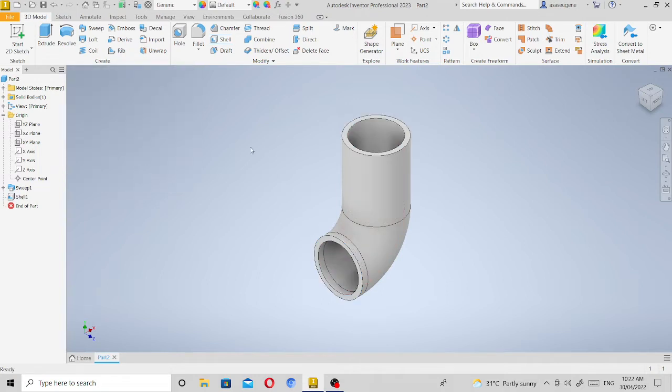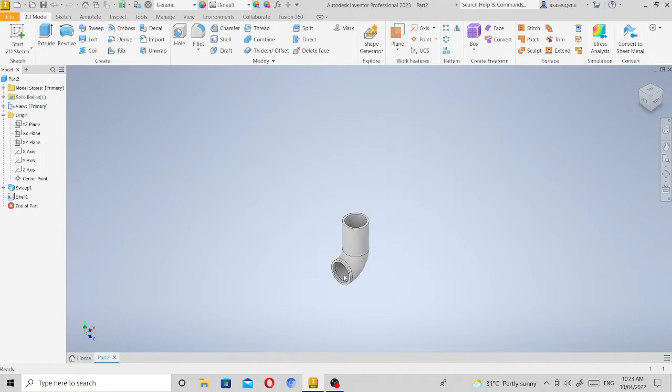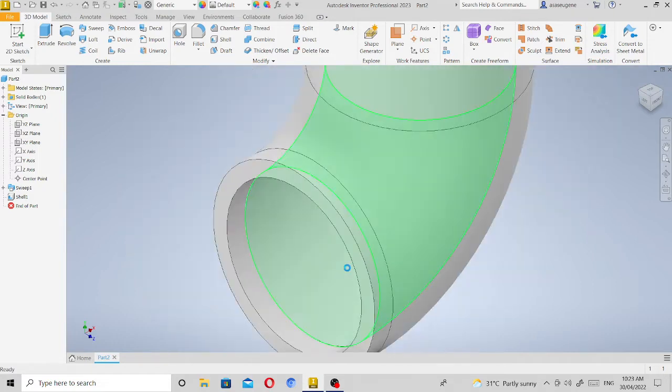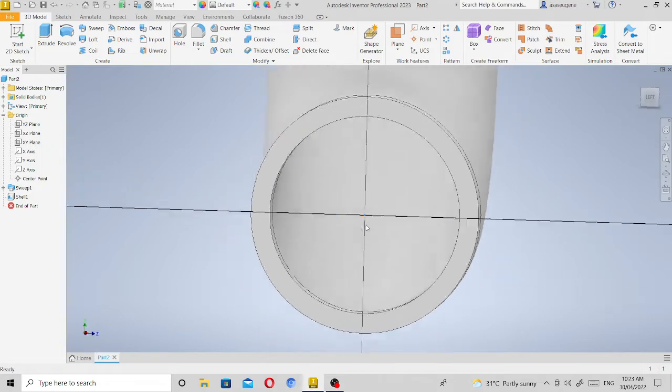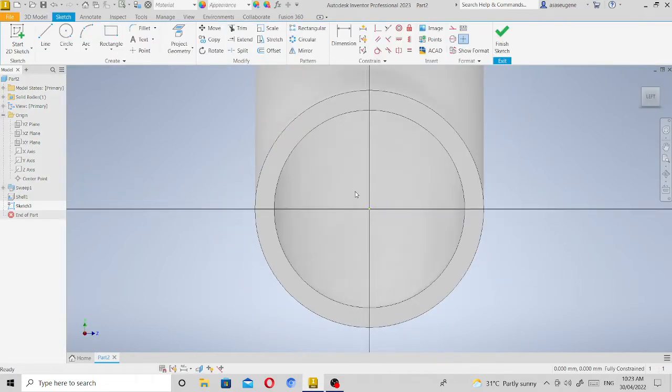And now I will make the flange here and the lower part. I will make the flange here after I finish this, the flange in this face. So I just zoom in so that I'll be able to select this face, and then this plus icon, create sketch. And next I will create another circle.